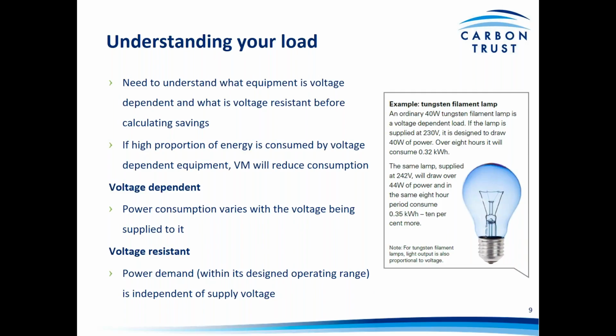First of all, we need to understand how much of the electrical equipment at the site is voltage dependent and what proportion of the energy costs this represents before we can start to look at calculating the potential savings from voltage management. If a high proportion of the energy at the site is consumed by equipment where the power demand is at least to some degree voltage dependent, then voltage management will reduce the energy consumption at the site.